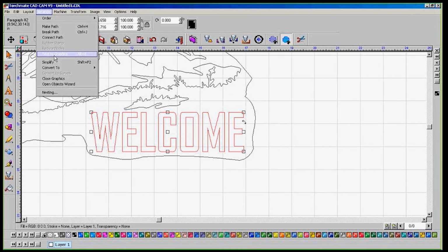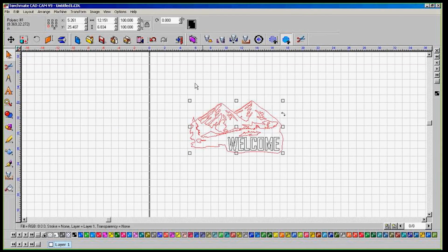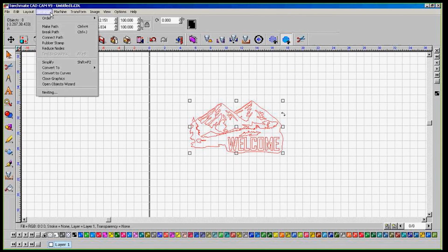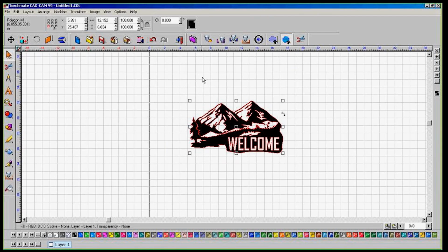As we all know, or some of us may not, we have the inside of this O that is floating, and so we're going to have to generate a bridge for the O in order for it to maintain that design. Being that the text that I chose works with just a square, I can go over to my rectangle tool and generate a rectangle that is going to be 0.2 wide and half an inch tall.